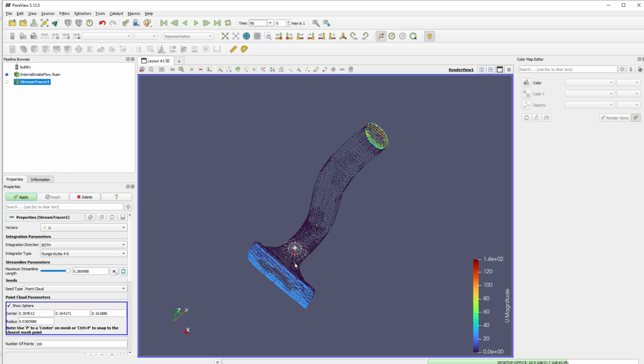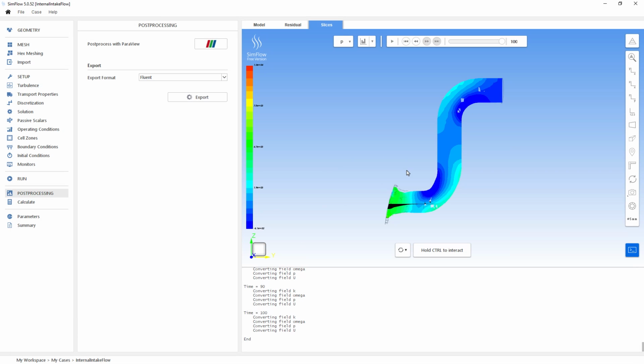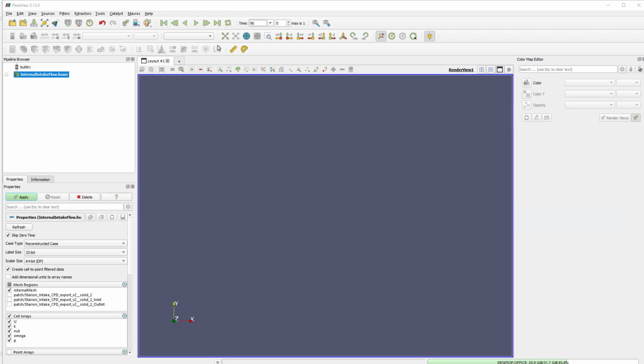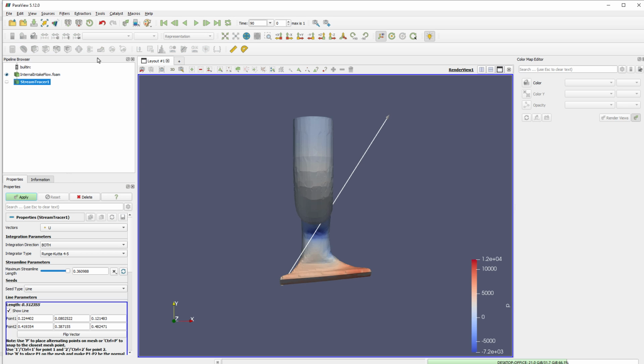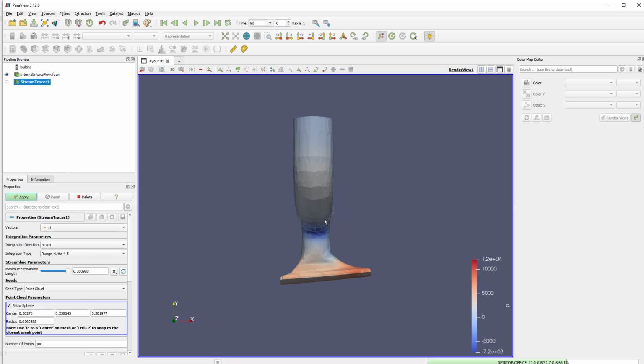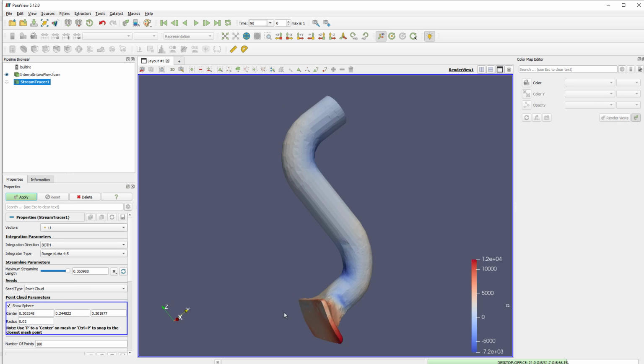Now, when we apply this, it crashed. I've had this happen before. All right, so I'm going to go ahead and push the data again. Again, we'll hit apply to bring everything in. Go to the setting. We will change this to point cloud. Put this here. And what I'm going to do is reduce the radius value. So right now it's 0.03. Let's make it 0.02 and try to get it inside.